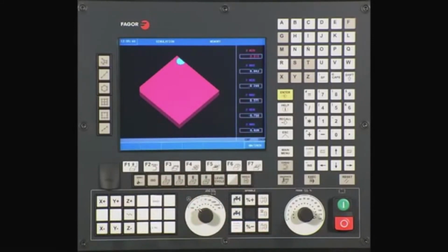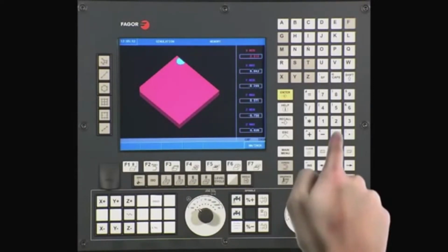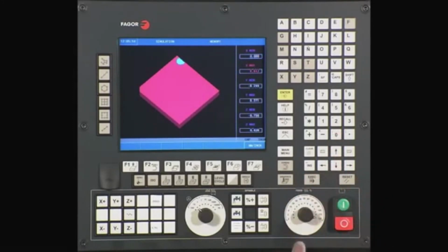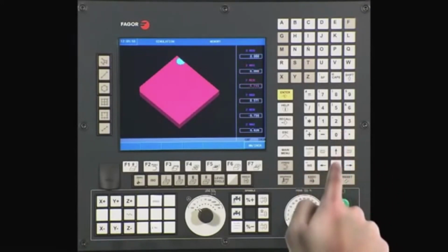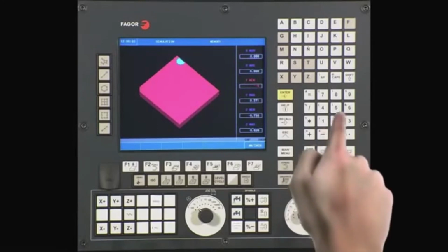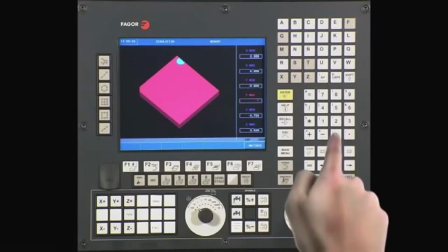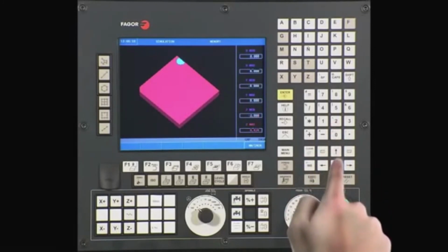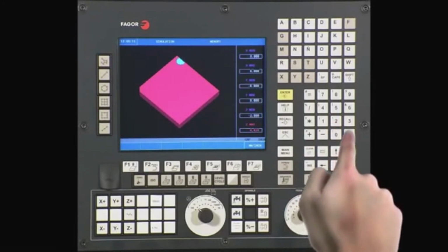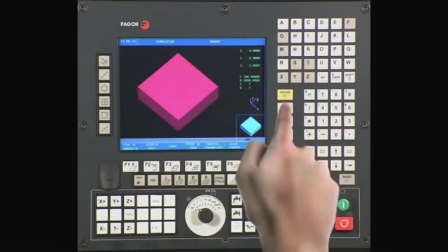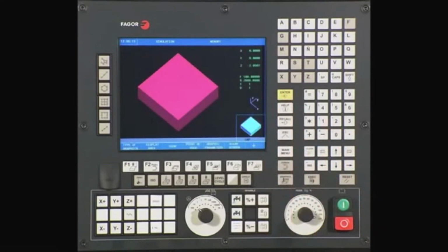We want to define the actual dimensions of our part so we have an accurate representation on screen. In this example, our min on X is 0. Press the down arrow key after each value is given. Our max on X is 6. Y min is -6. Y max is 0. Z min is -2. Z max is 100 thousandths. Type 0.1 and press Enter key to confirm the dimensions and save.